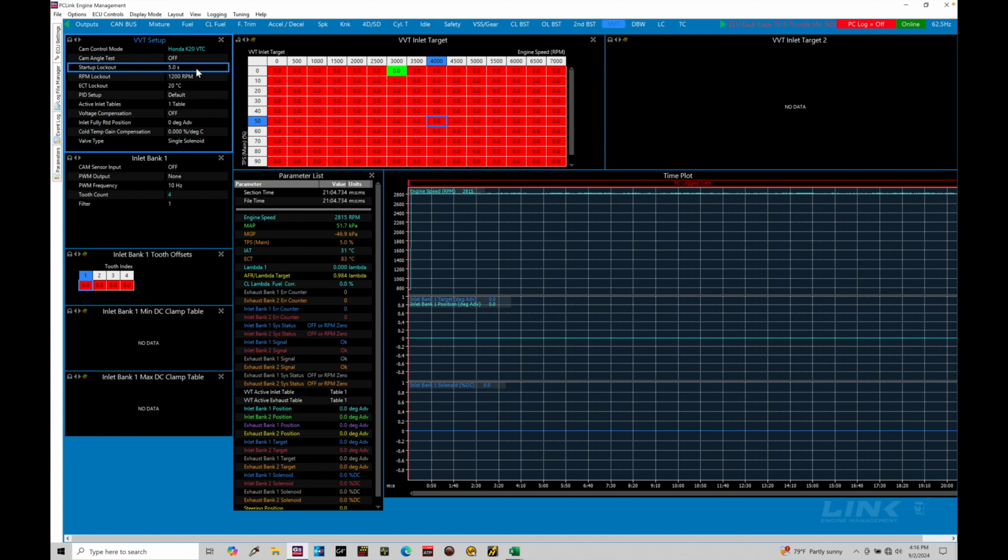So the actual oil flow solenoid, the pressure control solenoid, that's going to be pulse width modulated driven for any VVT control. We're going to be varying the duty cycle 0 to 100% to vary the oil pressure and flow to the cam gear. So it's, again, a closed loop system. We give it a target. It looks at the actual position of the movement and then adjusts the duty cycle output, either increasing or decreasing the pressure and flow to the cam gear so it meets that target. So again, everything is oil pressure driven.